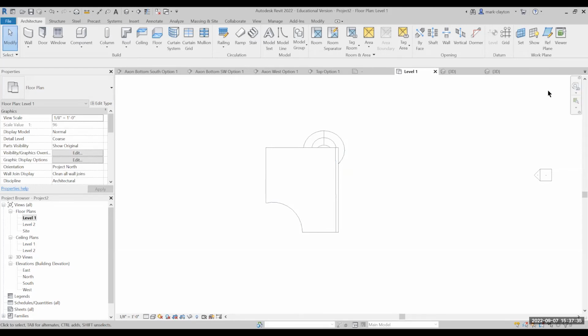And the way to do that and control it, basically you're going to use a section tool to cut a section through the model. And if I cut 20 sections through the model and plan on cutting them out of 1/8 inch thick plywood on the laser cutter, then I can take all those pieces together and glue them together and have a 20-foot model done at 1/8 inch scale, right?